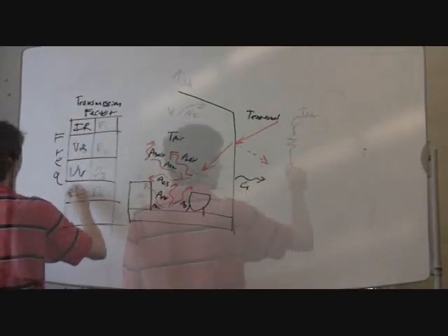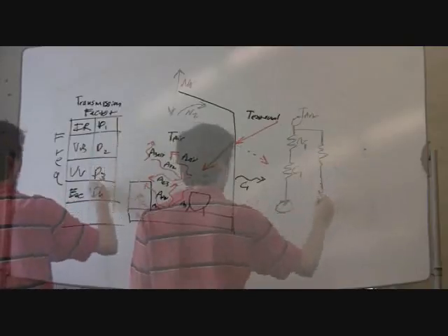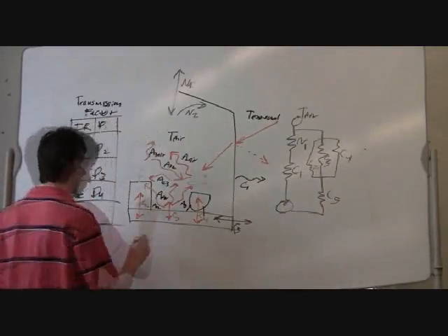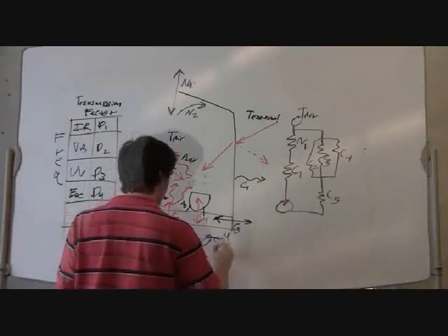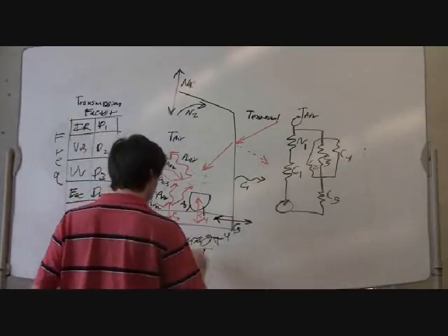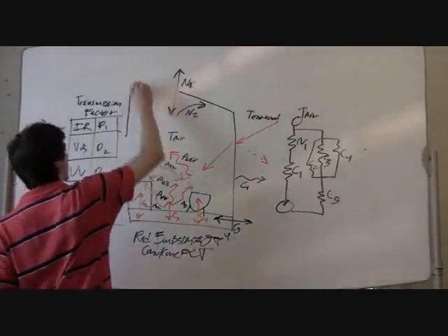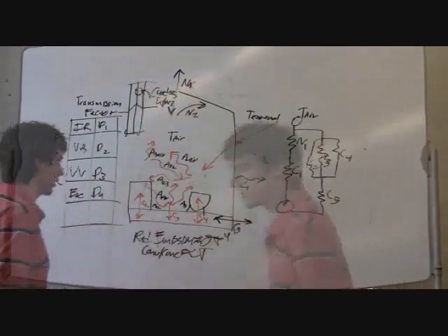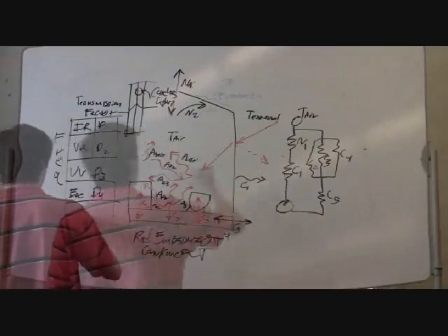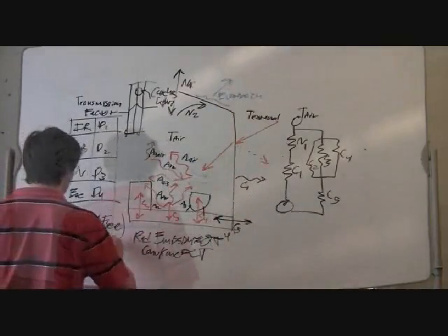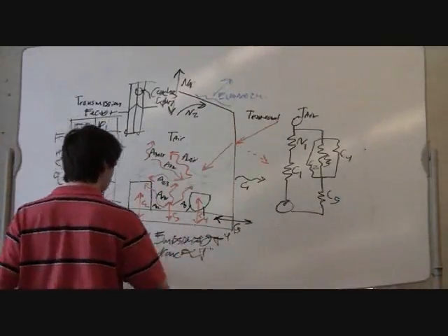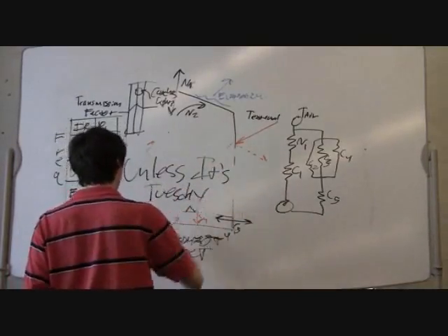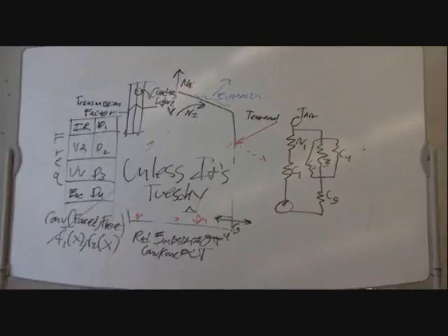For instance, the concrete of the floor will likely have an extremely different incident property than the plants themselves, and so what fraction of the greenhouse is the outer wall of the greenhouse is a heat flow circuit with parallel resistors shown to the right. Keeping in mind that these properties will change as the overall plant coverage and other shape factors begin to change, and bearing in mind that the circuit will have a different property for each frequency of radiation owing to the different incident properties, we can determine this by calculating the total convective resistance between the wall and the air in the greenhouse, depending on current air velocity assuming static conditions.